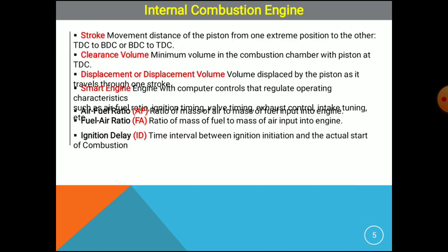Next is the stroke, the movement distance of the piston from one extreme position to the other. It might be from TDC to BDC, top dead center to bottom dead center, or bottom dead center to top dead center. That is called a stroke.